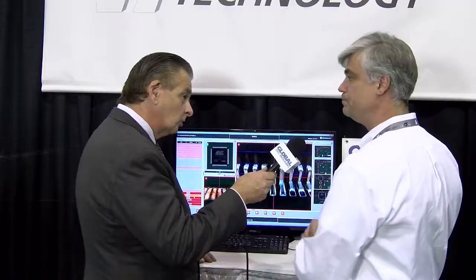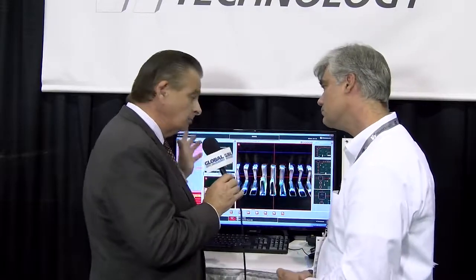We don't want to be changing programs and tolerances just by doing this, but we want to flag a programmer or a quality manager to look at the data and ask: do I need to change my tolerances? Do I need to fine-tune my programs? Or do I just need to retrain my operators? Or do I have an issue with the process somewhere else that's outside of my control? So I think the starting point here is that you're using true metrology across both your SPI and your AOI, so you're able to give real data back and forth.